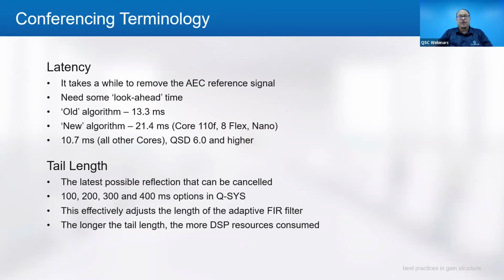But when you adjust it, it adjusts the length of the FIR filter. The longer the tail length, the more DSP resources are consumed. It takes time to do that.